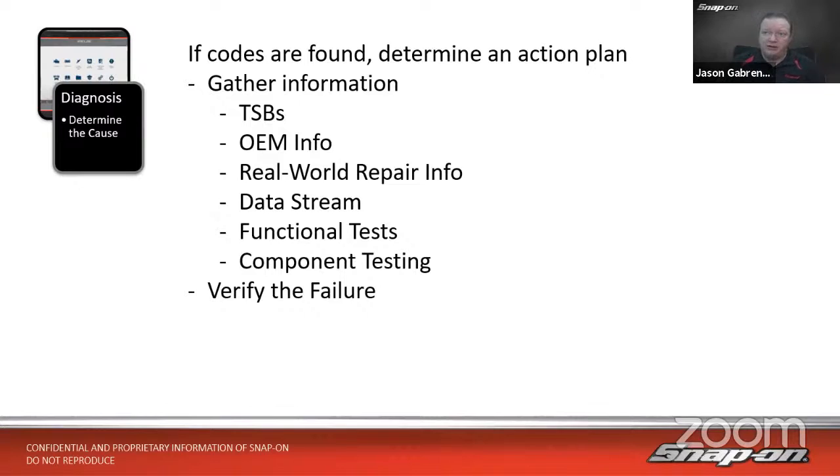And of course, at that point, if you saw the last time we were here, the data stream indicated that there's excessive vacuum in the fuel tank, even though it was commanding the vent valve to be open. So that shouldn't happen, because we shouldn't be able to build vacuum in a fuel tank with the vent valve open. So that led us to believe, well, maybe it is that vent valve. So next thing we did is use a functional test. Use a functional test and our senses to see, turn it on and off, does it click, does it open and close. In this case, we functionally tested it and it did not functionally work. So it was not opening or closing, couldn't hear it, couldn't feel it, seemed like it's not working.